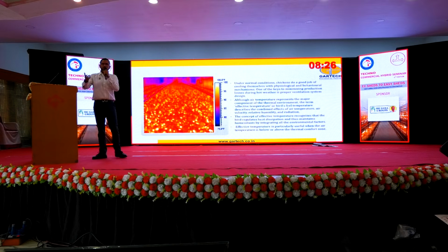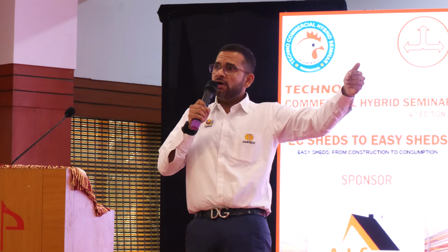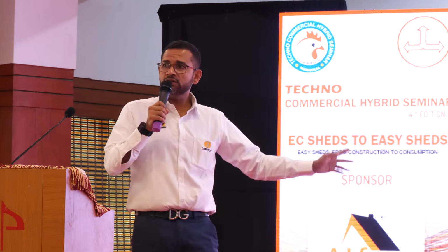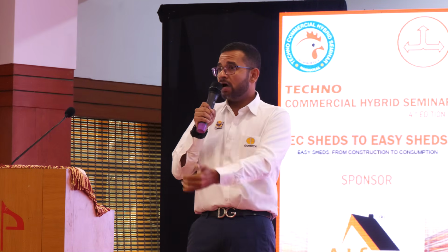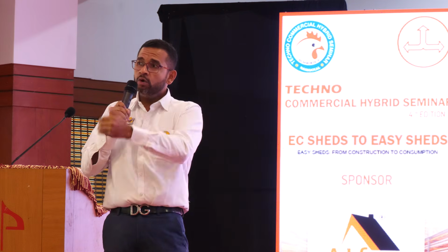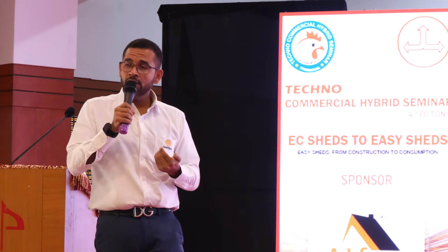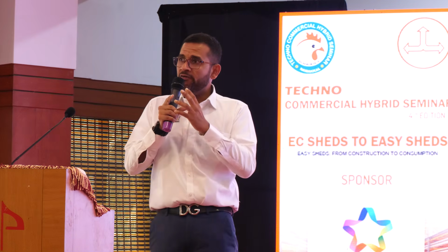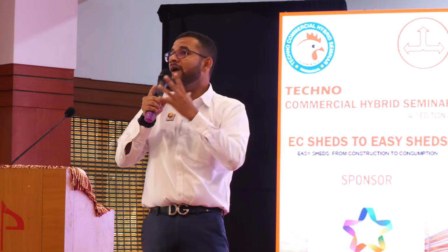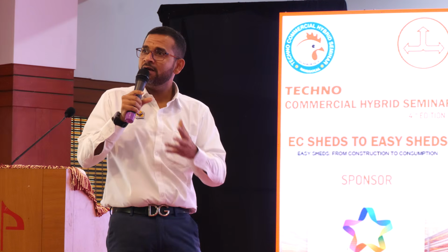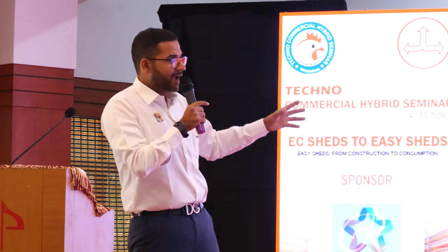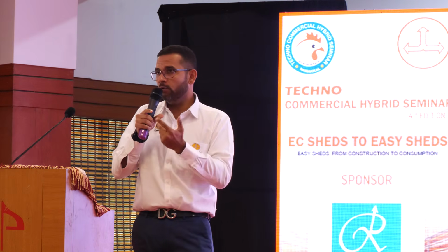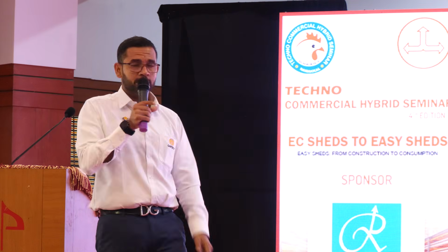And we spoke about this poultry industry. In the last 50 years, we have gone from chickens becoming 2 kilos in about 2.5 months to now achieving 2 kilos of body weight in under 4 weeks. So basically the amount of heat generated has gone from the same amount of heat generated over 2.5 months to 25 days. So it is a very intensive kind of heat loss that we are experiencing in the same kind of house. For that, environmental control is becoming more and more important. In fact, it has become hypercritical today.